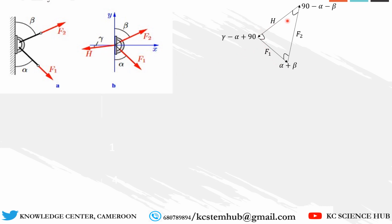But now notice that H is entering, F1 is leaving, and this is not the angle between those two vectors. So what do I have to do? I have to take 180 minus this thing I've just gotten here, and if you take 180 minus that, you get this result. You take your time, practice what I'm saying. Each thing I say, just write it down, and then you see how it makes sense at the end of the day.